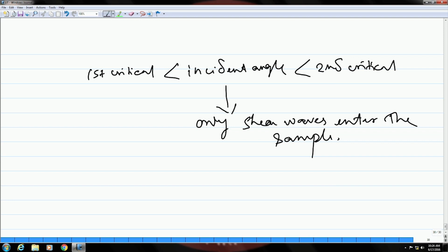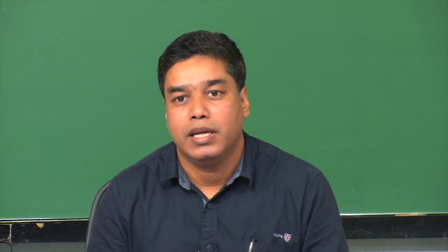Okay. So, in order to do that, you have to ensure that you have only shear waves entering the sample, and for that the incident angle has to be in between first critical and second critical angle.